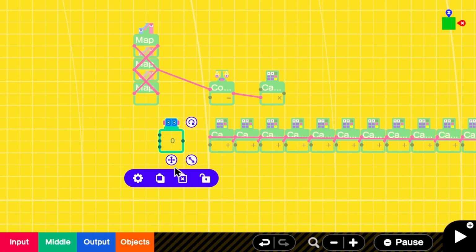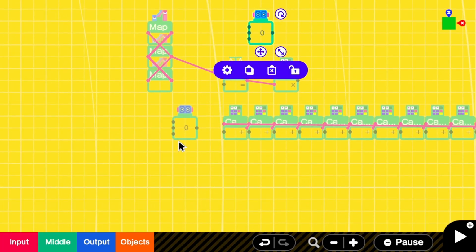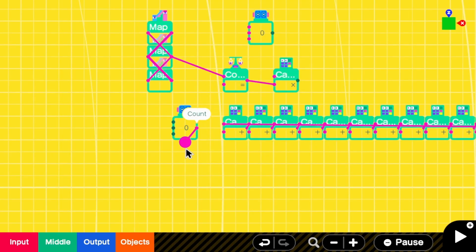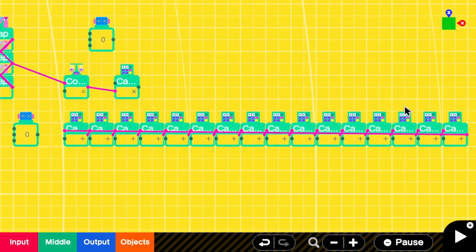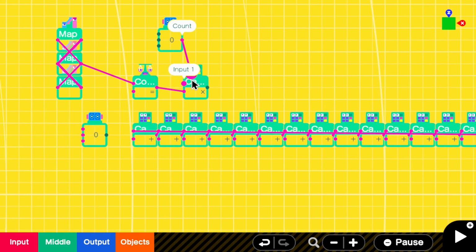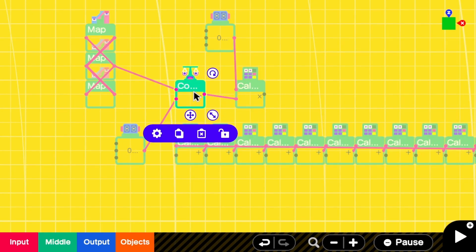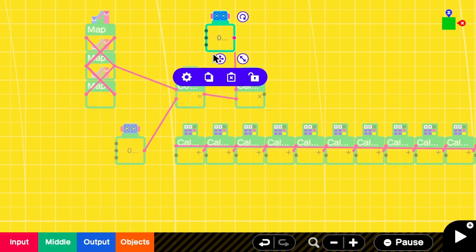So for example here, let's say this counter is the index. So this is the number that chooses which of these we want to access. And let's say this is the input. So let's connect the input, one of the inputs of the multiplier here, and then the index to one of the inputs of the comparator. So the comparison is between the subframe clock and the index, and that goes to the multiply, which has this comparison and the input, whatever input we want.